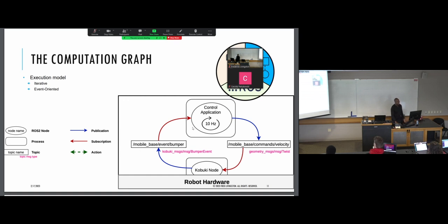And this is called a computation graph here. And then you can actually see the actual frequency, the control loop of, like, this laser scan might be running at 200 hertz, publishing data. Your IMU might be only publishing at 50 hertz. So you can see the rate of the sensor going across the network as well. And what's good about ROS here, even though I'm doing everything in simulation, if that was hooked up and we had this shared IP address, they will automatically auto-discover, which is in ROS 2, as long as I'm on the subnet, I could communicate with that and start listening to topics.